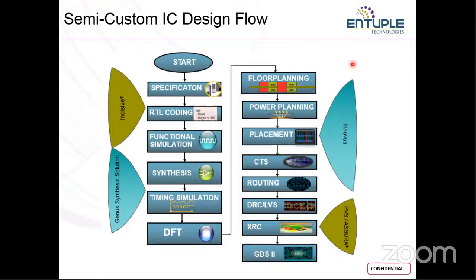So if you are talking about sequential circuits, then you need clock signals, right? Clocks are going to be the activating part of your circuit. Without a clock input, your input won't go to the next level, or your device doesn't take your input. So that is the reason why we have a clock tree synthesis, but in combinational circuits these are not required.